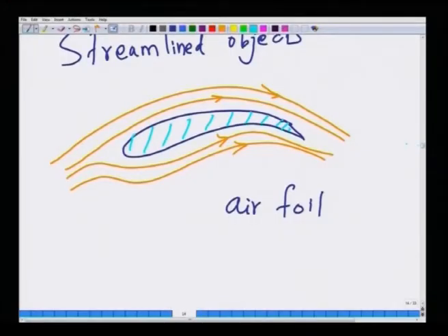So, in streamlined bodies the form drag is minimal compared to objects like spheres or cylinders, where there is a significant form drag. The form drag is itself due to the pressure asymmetry between the fore and aft of a symmetric body like a cylinder, and why that pressure asymmetry occurs in experiments is because of flow separation, which we will come to shortly.